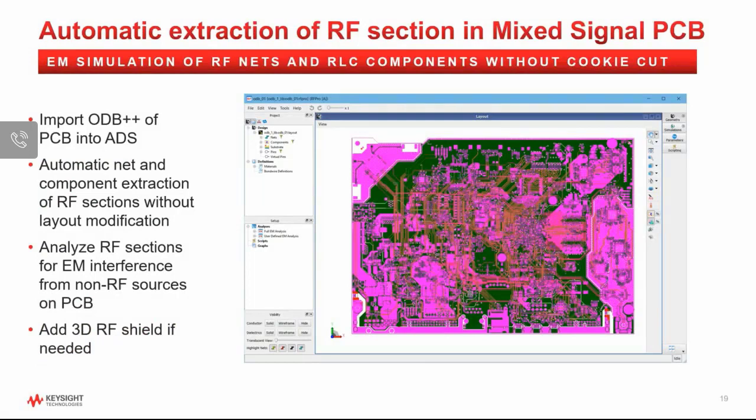Thanks, Jack. Now I want to share how a mixed signal PCB board with an RF section can be imported and simulated with RFPro. This is a digital TV tuner board from an Italian company, Seiko, who has kindly shared their design methodology with us. The PCB ODB++ file was imported into ADS as shown.